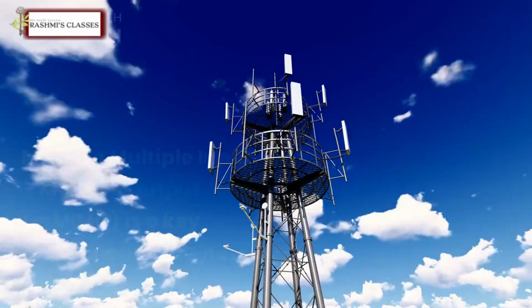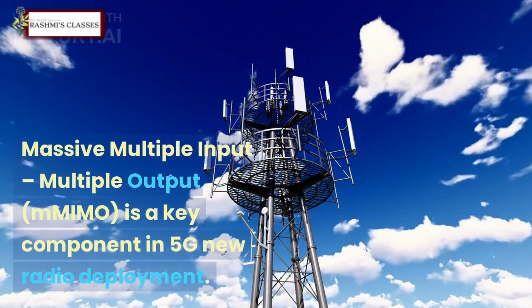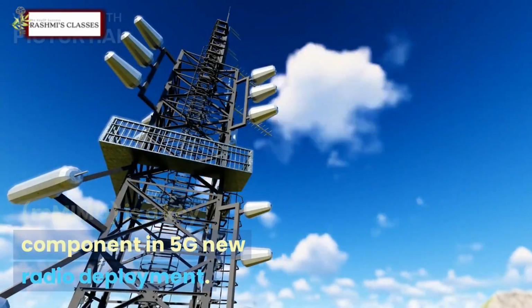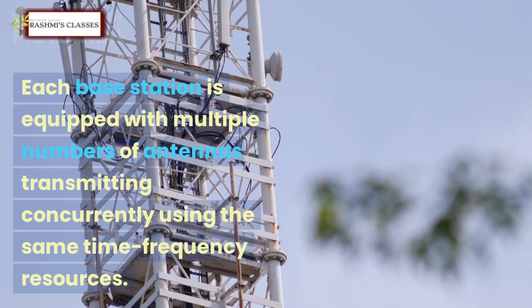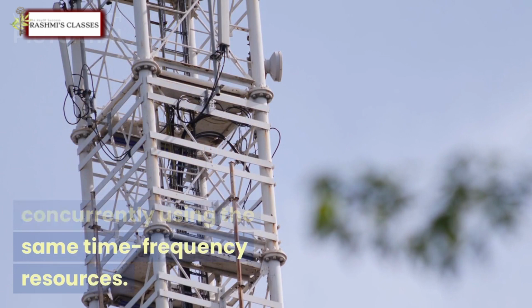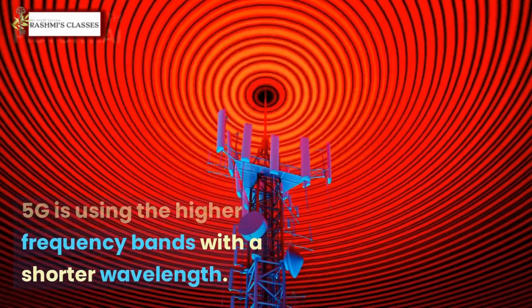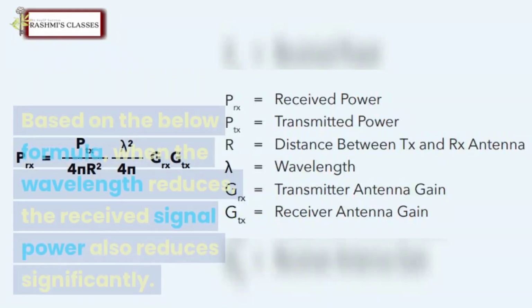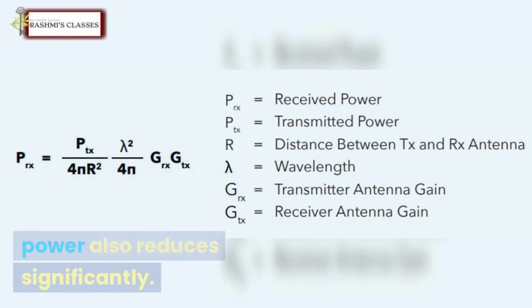Massive MIMO. Massive multiple input, multiple output, MIMO, is a key component in 5G new radio deployment. Each base station is equipped with multiple numbers of antennas transmitting concurrently using the same time frequency resources. 5G is using the higher frequency bands with a shorter wavelength. Based on the below formula, when the wavelength reduces, the received signal power also reduces significantly.